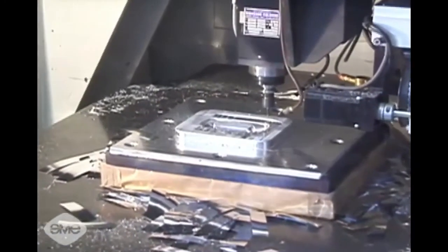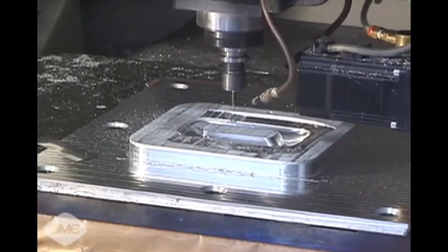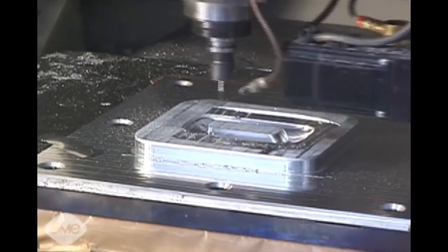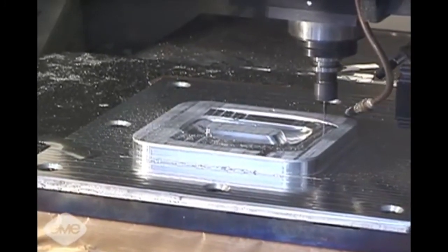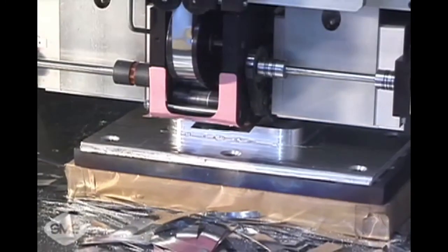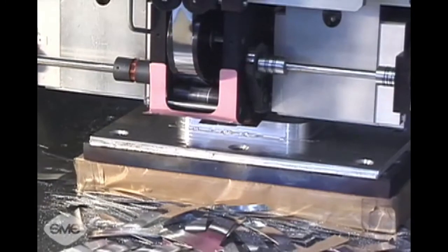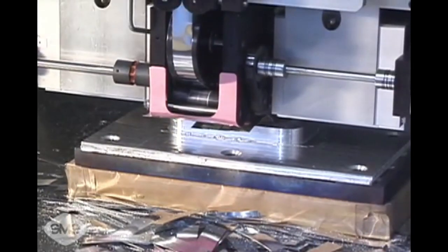Like other rapid prototyping processes, ultrasonic consolidation also allows for the buildup of complex geometries, overhangs, and enclosures within a part. Ultrasonic consolidation can be used to bond a variety of similar and dissimilar metals, as well as certain ceramic metal combinations.